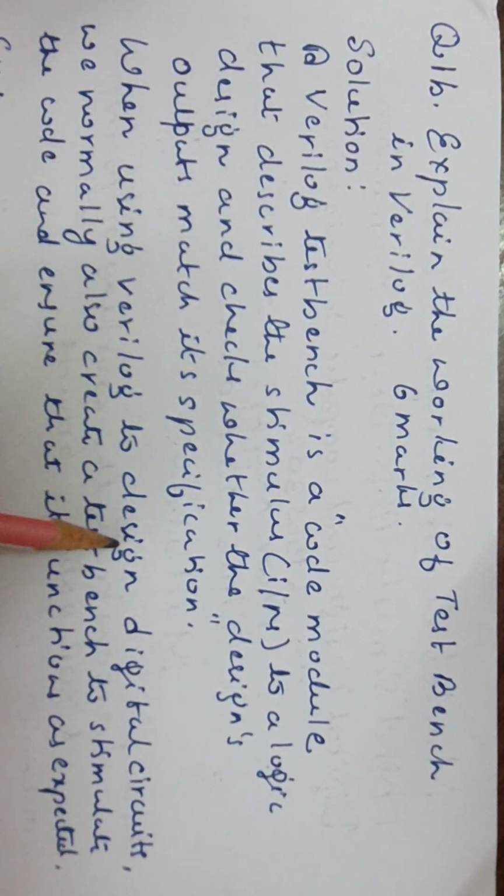When using Verilog to design digital circuits, we normally also create a test bench to stimulate the code and ensure that it functions as expected. Means first we write a code module or a program in Verilog to design a logic circuit. Next we write another code module or Verilog program called a test bench, which will give the inputs to the first one to check whether the circuit designed in it functions as expected, yes or no. Right? Next we shall see Verilog code for a simple logic circuit, and another code module called a test bench, which will give the inputs to this first one.